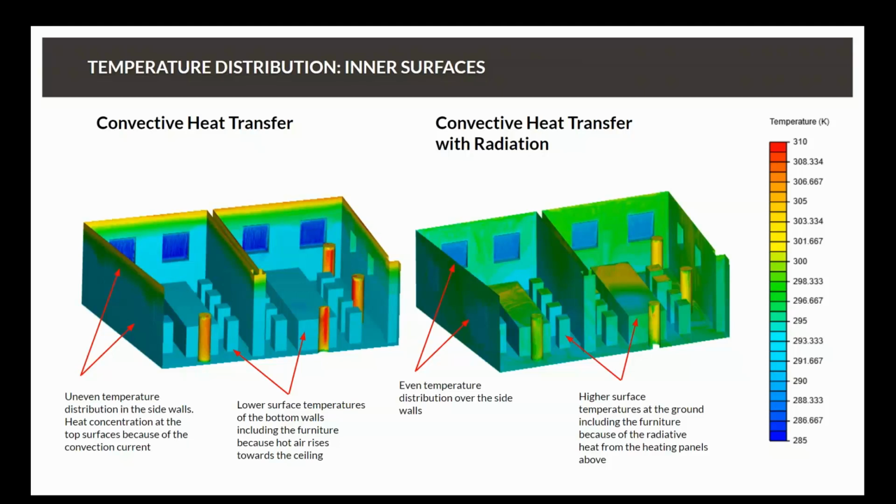On the right-hand side, the heat is being radiated to them from the radiative panels on the ceiling, which are essentially the same as radiators. They're basically a heat source that radiates outwards. So they're radiating to the tables, and also some of the radiation from the people would also basically heat up the local regions.